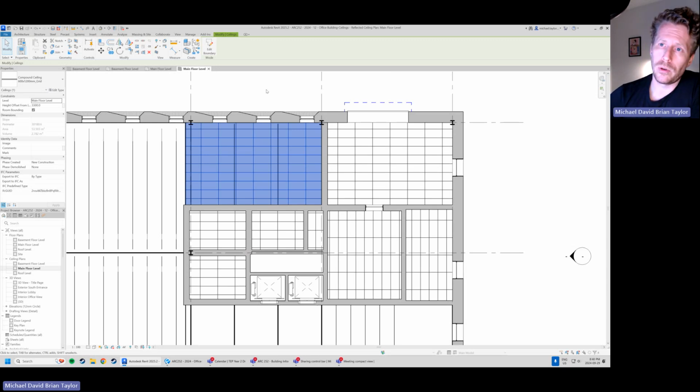So right now, inside of our properties palette, we've got what are called the instance parameters, right? So these are all instances of pieces of the building. It's every piece we could set separately, an instance. If we wanted to edit the overall type parameter of this family, we can jump up here to our edit type command, click that.